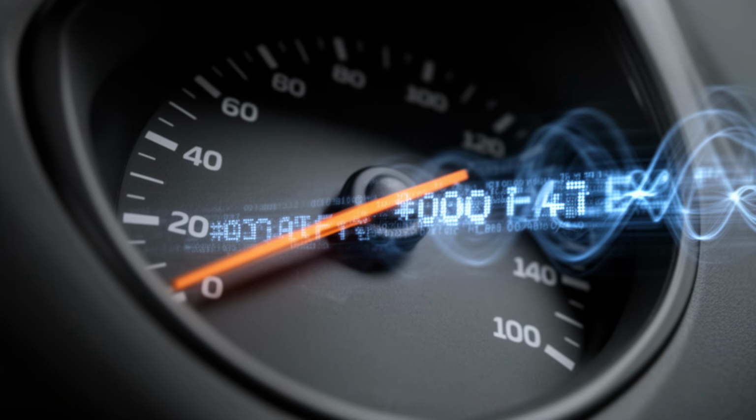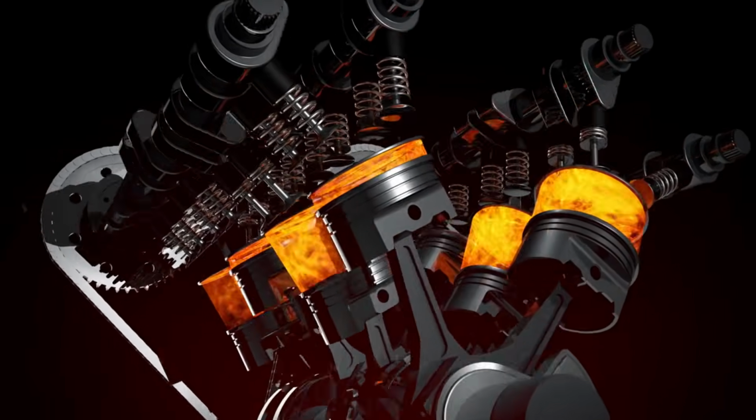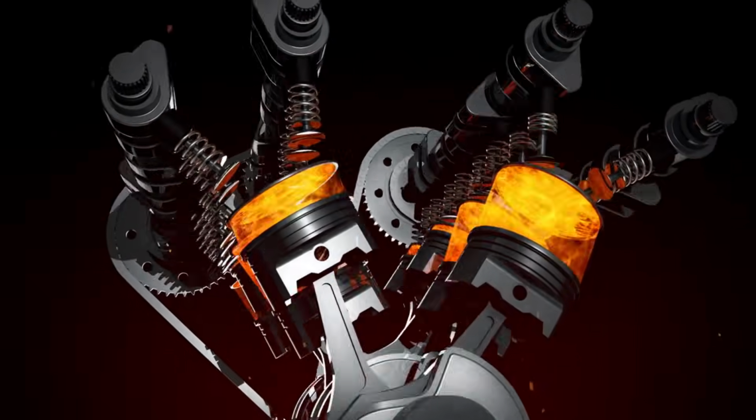The ECU can only calculate that ratio correctly if the MAF sensor gives it accurate data. The sensor is the primary input. Everything downstream, injector pulse width, ignition timing, fuel pressure modulation, is a calculation built on top of the MAF reading.